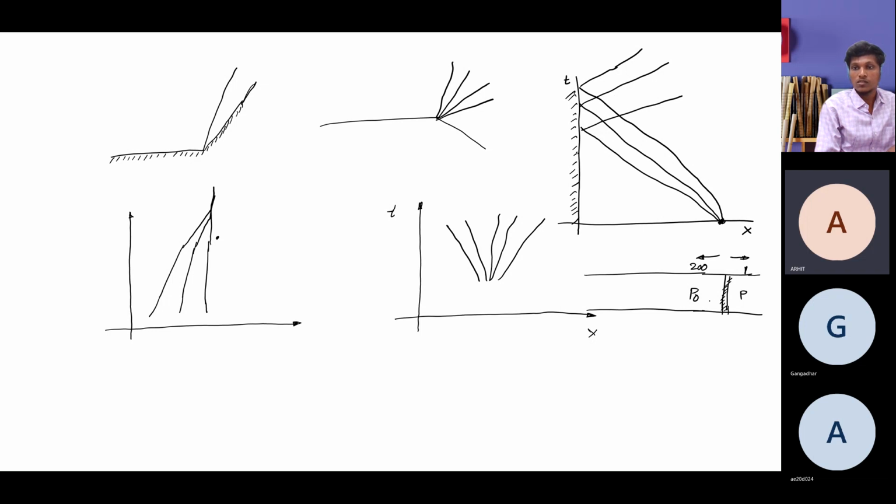Okay, so in case of expansion waves, yeah, shock tubes. In case of shock tubes, yes, this is what we call shock tubes. So in the shock tubes, your normal shock and expansion waves both exist together. They cannot exist individually because it starts from zero relative velocity, right? Yes, sir. So both your normal shock and your expansion waves exist, and whatever concept you are trying to visualize, you can understand from this shock tube and the backward running characteristics or rightward running characteristics. If you draw those two, you can see.